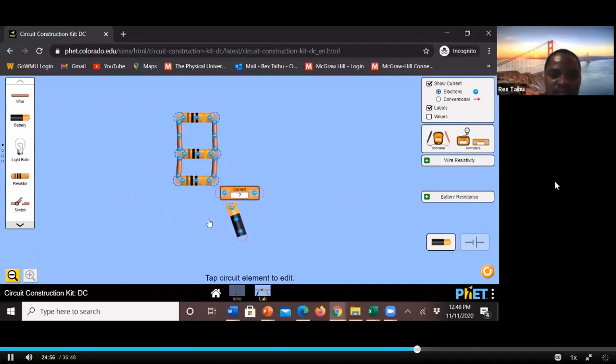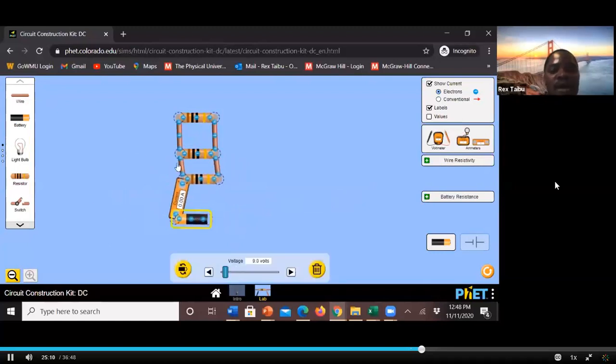Then the battery is here, but I need to put an ammeter so I can check a reading. The battery is like that. It doesn't matter here because any branch has the same current from the power supply, either left or right. Anyway, we have the current there, and then we have a wire here to there. Now we have our parallel circuit. Set this one to 80, set this one to 90, set this one to 100. Then take readings again.